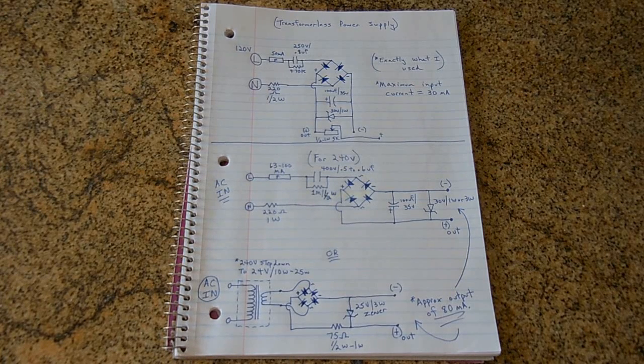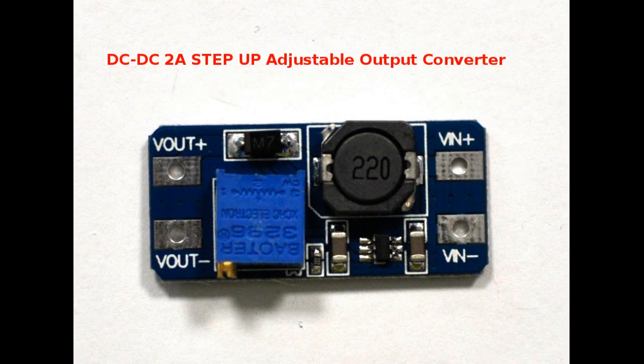Now, one more thing I wanted to add. If you would like to use this LED strip light inside your vehicle, which operates between 12.5 volts with the engine turned off and around 14.25 with the engine running with the alternator charging the battery, then you can always pick up one of these very inexpensive DC to DC step-up converters like you see in the image right here. You can connect the input to your vehicle's electrical system and then set the output at 25 volts, and then you can power this light strip with no problem at all.